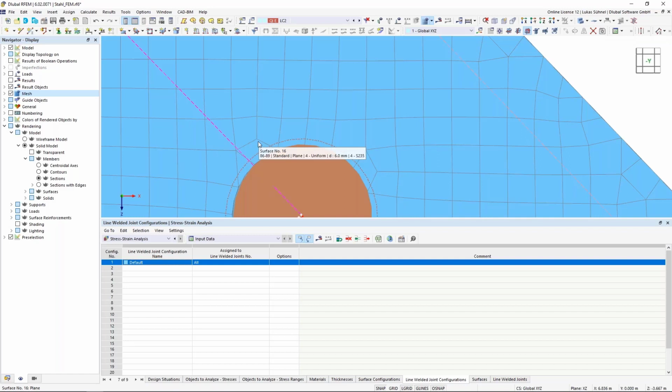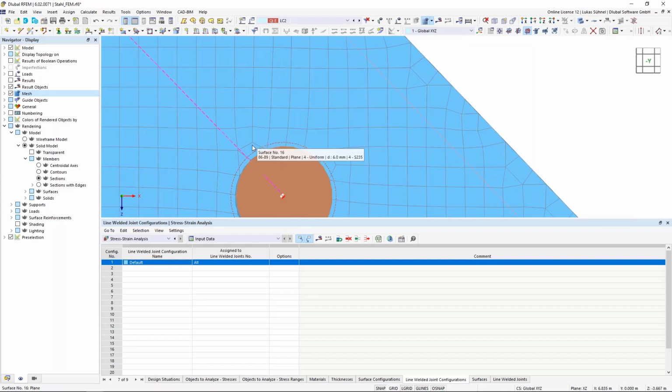So we take a look at each FE element and we reduce the stiffness of those FE elements where the stress is exceeding the limit stress. If we reduce the stiffness, it means they will deform much more than the other elements with the regular stiffness, which will take over more of those forces until they maybe also reach the limit stress. Then we will reduce the stiffness again, and so on. That's the logic that we're using here. So we take a look at each FE element, and since we do it on this FE element basis, we should also check the results on FE elements.